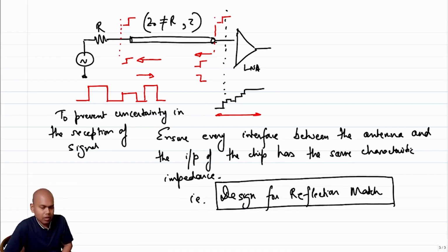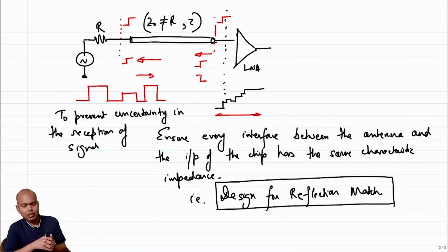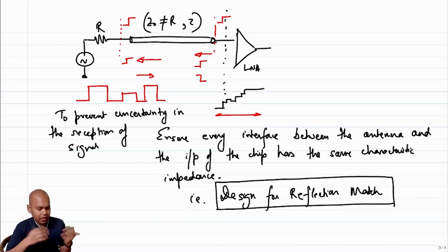And if they are much smaller than the wavelength, then you don't really care about reflections, because the reflected wave and the incident wave will almost have the same phase, right? So if the reflected and the incident wave almost have the same phase, then it's not a problem.